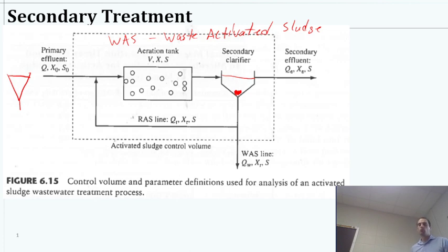So then once we send it through the clarifier, as we'll see, this X in the effluent should be pretty small. That way we capture all of the X that we produced into the recycle and into the waste. So we'll get into some more details about all of that, specifically later in this lecture and in our next one. But that's kind of the big picture of what's going on with our biological treatment, okay?